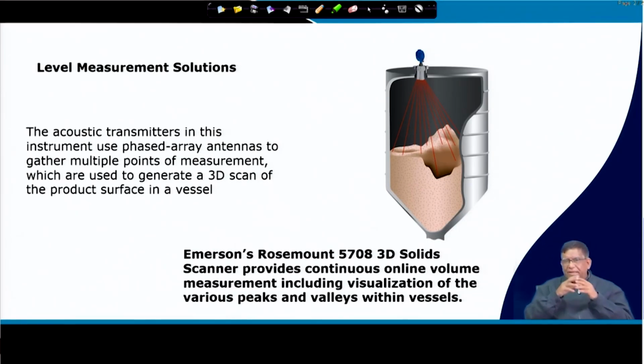Now, as I was telling you, if you are doing this loading and the material is coming and getting filled into the bunker, if it gets overfilled and you do not give a message to the incoming material flow, then if it is by conveyor, that conveyor needs to be stopped, and along with that all the subsequent conveyors will have to be stopped. To do that we need to monitor how the bunker is getting filled up. This is again a place where mechatronics and instrumentation are used.